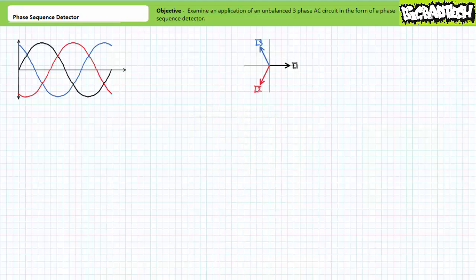You are no doubt aware that a three-phase AC system is characterized by three voltage waveforms with the same magnitude and frequency offset from each other by a relative 120 degrees. A common light industrial three-phase AC system available in the United States is characterized by 120-volt line-to-neutral differentials, 208-volt line-to-line differentials with an excitation frequency of 60 Hz.